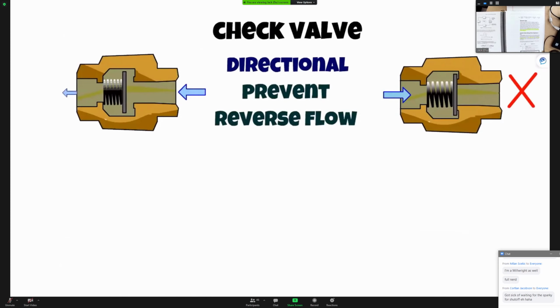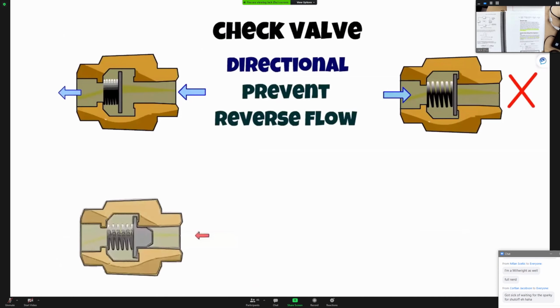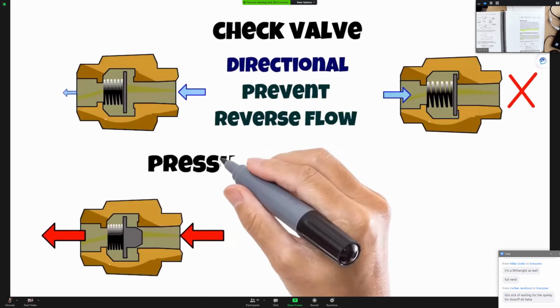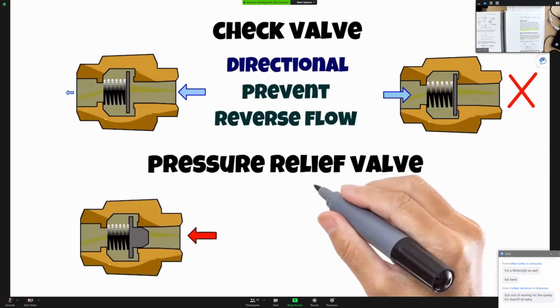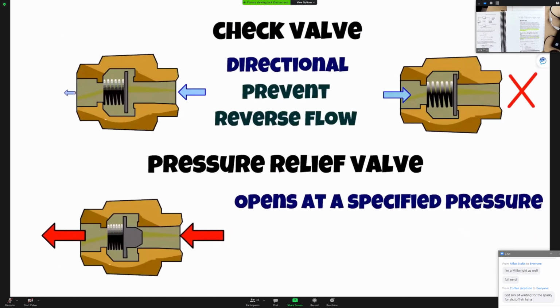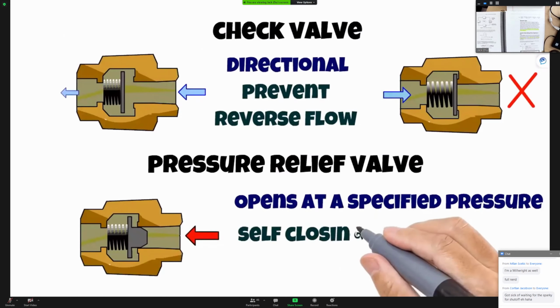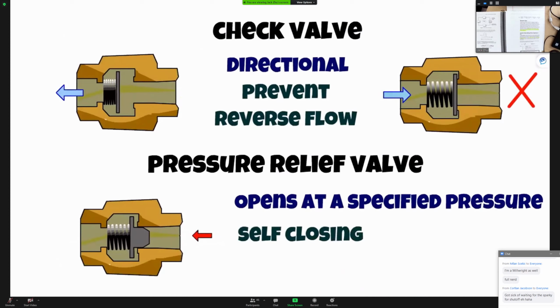There's another variation to check valves with a small change. If the check valve seal is extended, then a check valve can be made into a pressure relief valve, where the valve opens and expels excess pressure buildup. The diagram shows a preset relief valve, where the spring is designed and calibrated to reduce pressure buildup. The spring compresses until the seal is pushed past the sealing chamber, and then pressure is released until the spring overpowers the pressure and reseals the valve.